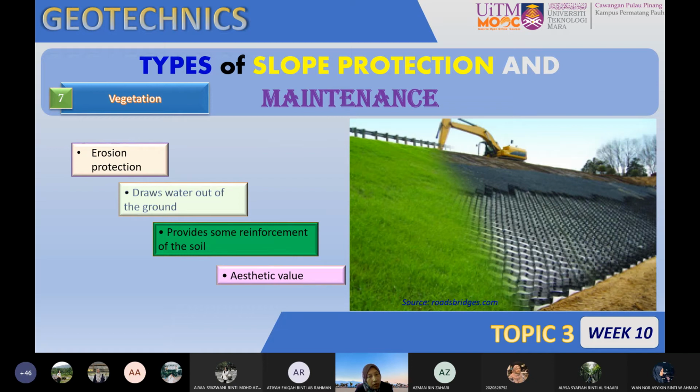And then the last part, using vegetation, is very simple, but it can also come together after unloading or changing the geometry of the slope, or using bearing piles or a retaining wall, and then you finally place roots or vegetation to cover up the process involved. Let's say you have a slope cut, you excavate the slope and lay a geomembrane, for example, and lastly, after filling with some fill material, you close the surface using vegetation.